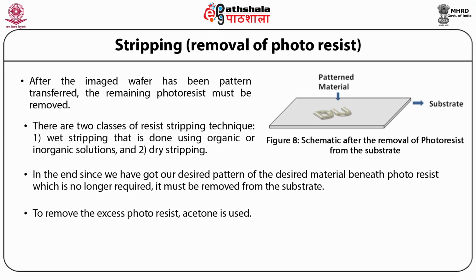To remove the excess photoresist, acetone is used. Also, we can remove the photoresist using oxygen plasma. The figure given here, figure 8, shows the schematic after the removal of photoresist from the substrate.